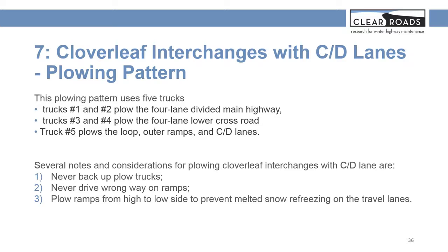The configuration is more complicated, so there are some notes for the operators. Never pull back and do not drive the wrong way, and plow ramps from the right to the lower side. Always push snow to the lower side to prevent the melted snow from refreezing.